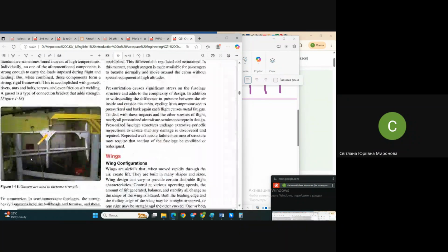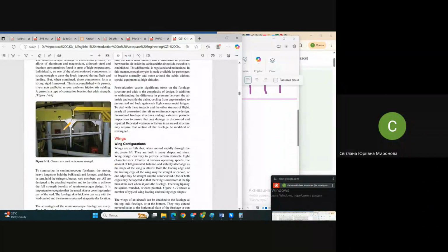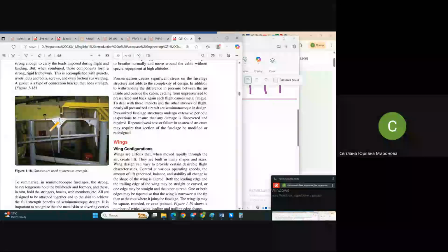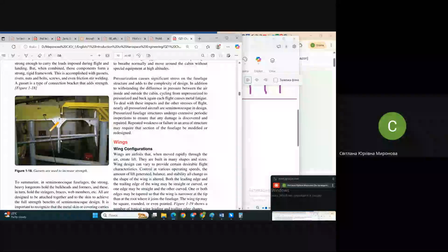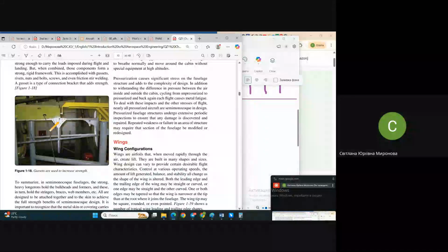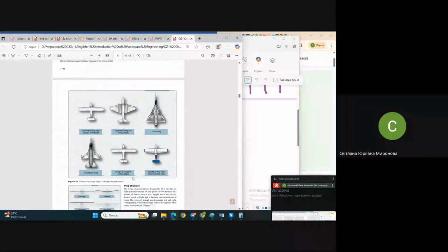And the additional elements mentioned here are like doubling pieces of skin, which reinforce the places of joining of transversal and longitudinal elements, which are already joined with stiffeners, knees, and so on. Not everywhere, but in some places additional elements are given, with the names gussets, pads, and so on.